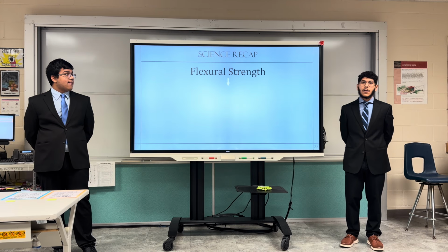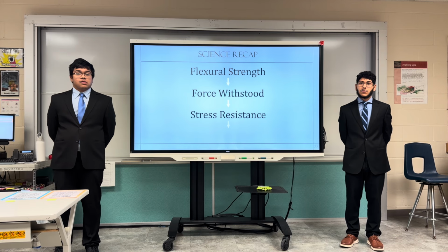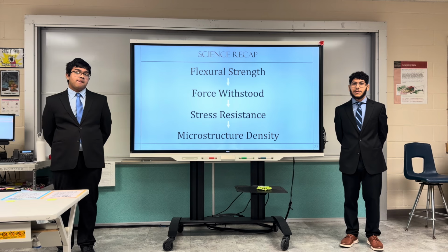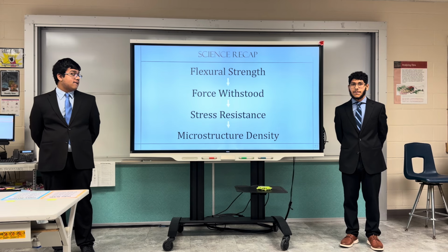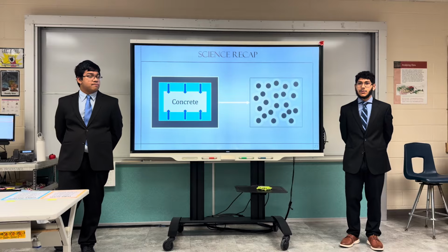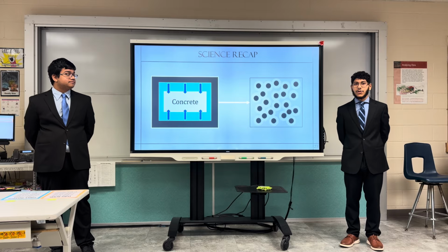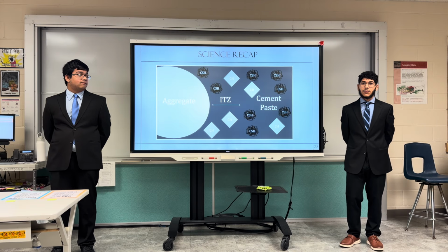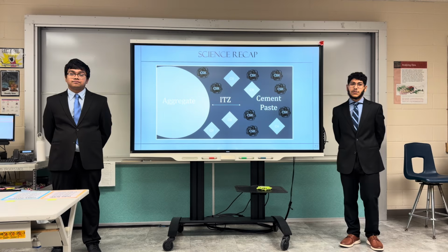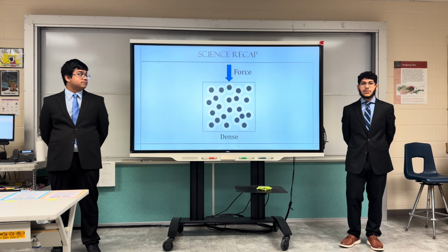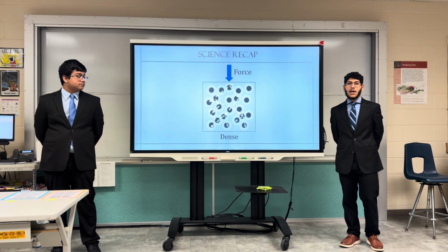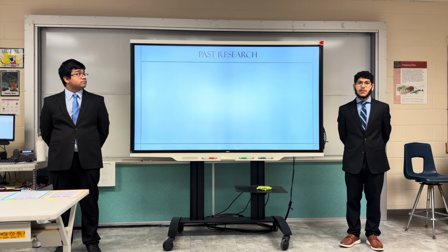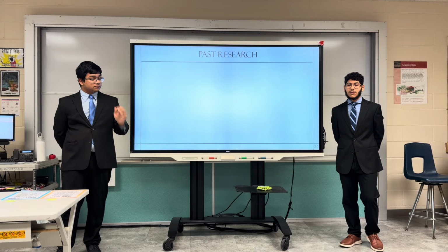So as we said, the flexural strength is dependent on the amount of force withstood by the concrete, which is ultimately determined by the amount of stress it can resist, and that is determined by the density of the internal microstructure. And that microstructure can be developed through continued chemical reactions, which are prolonged through curing. Because when the internal microstructure is still filled with the binding agent produced by these chemical reactions, when a force is applied, the force can evenly disperse throughout the concrete as they concentrate in certain areas, allowing less stress to build up, thus more force withstood before the concrete breaks, leading us to say that curing does in fact lead to an increase in flexural strength.